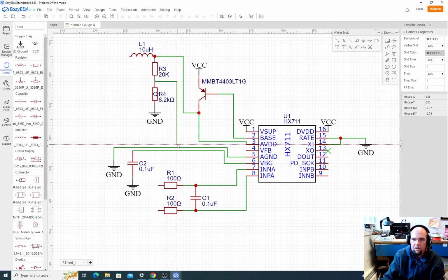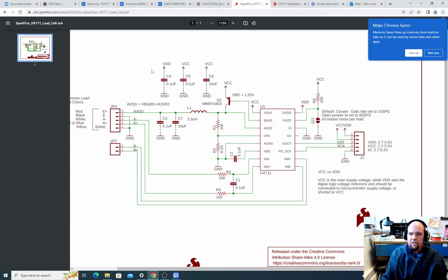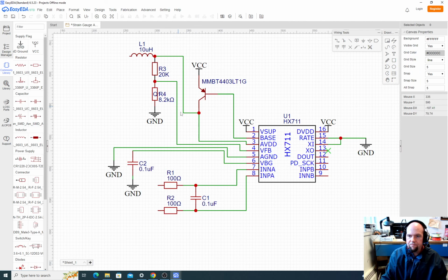Okay. So the wire between the resistors went to VFB, the top side of the divider went to the side of the inductor, and the bottom side went to ground. Sanity check. Middle went to VFB, bottom side went to ground, top side went to the inductor.